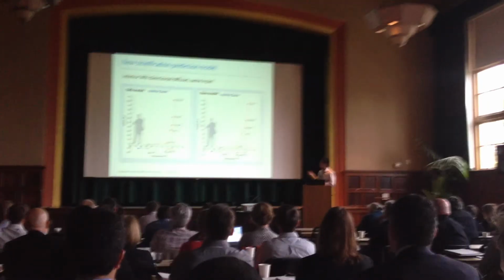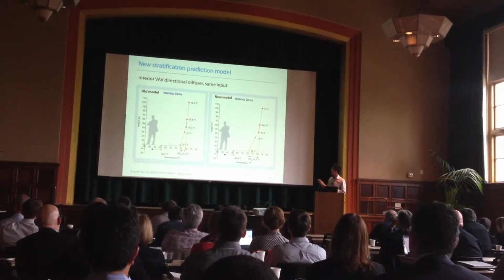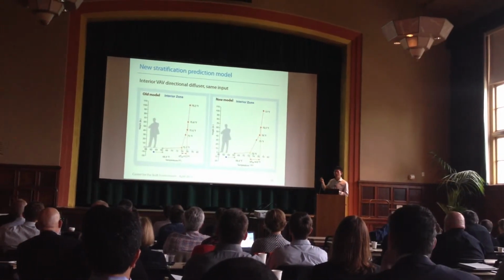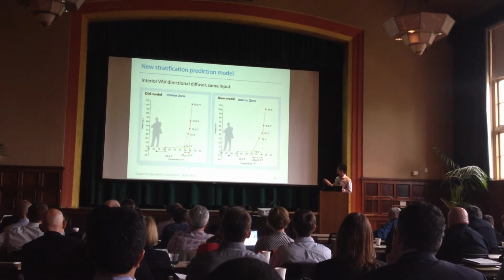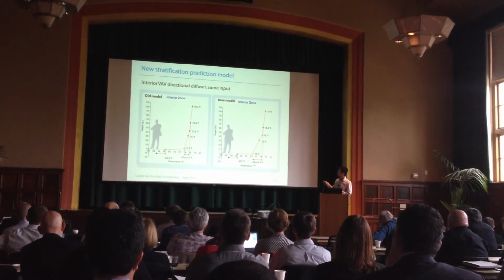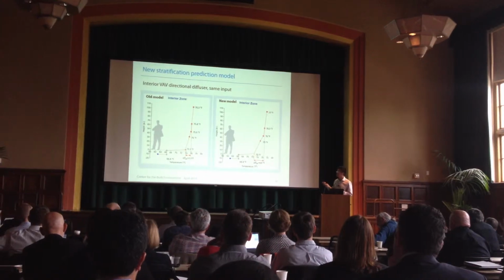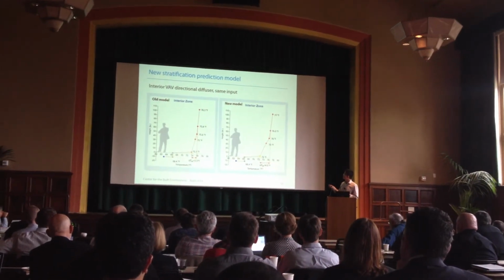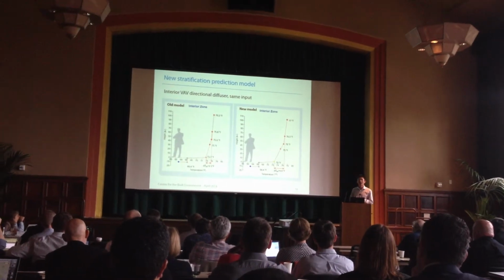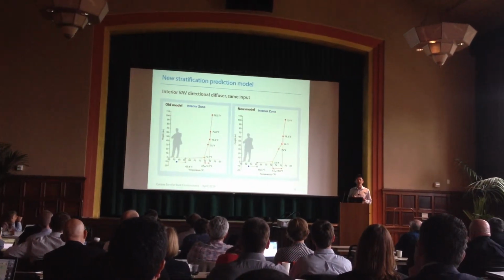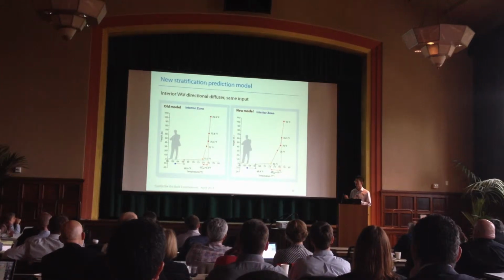And the difference is actually quite large, because the temperature between the head and ankle could be as much as 2 degrees comparing the old and the new models. So we can imagine if you use the set point from the old model, it will result in the overcooling of the space, so it will also bring discomfort to the users.